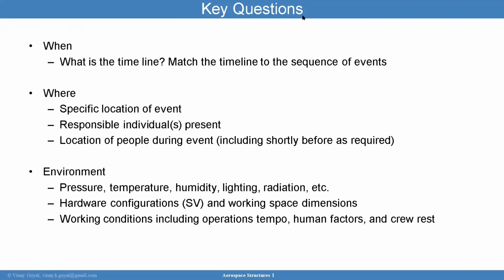Also, it's important to gather a clear timeline. In the spacecraft and launch vehicle industry, this is huge. If you have a failure that occurred at T plus 1 minute 20 seconds, you can look at the telemetry and see if there's anything weird going on prior to the failure. In fact, many anomaly investigations in aircraft, launch vehicle, and spacecraft are not solved using timelines, but timelines provide significant guidance because they give you telemetry, acceleration data, thermal data, strain gauges, accelerometers, pressure sensors. Maybe the pressure sensor was acting weird in one of the valves, and then the failure occurred. Well, maybe something was going on with that valve. That's why it's important to pay attention to the timeline of events and create a timeline that syncs with the video as well.